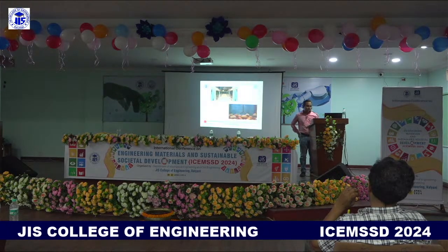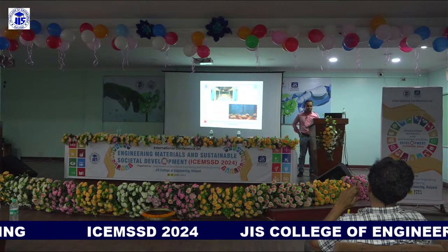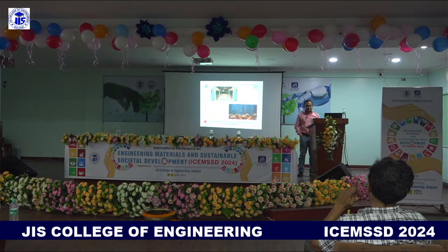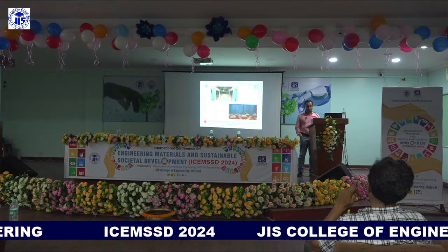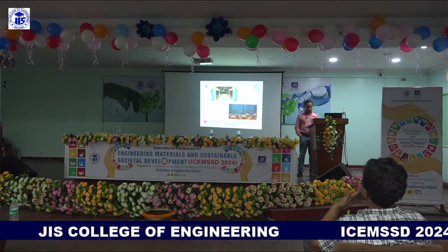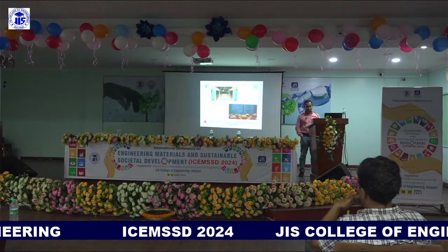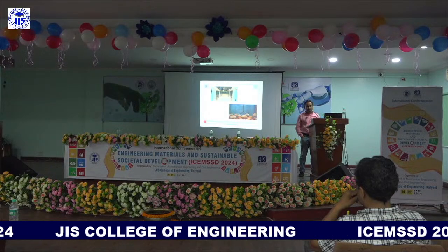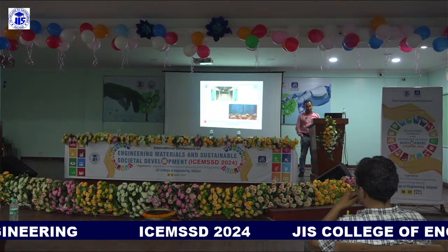For this kind of experiment, initially we use some non-dimensional numbers. In your fluid mechanics book, you will see many kinds of non-dimensional numbers, like the Froude number, Reynolds number, Weber number, Mach number, and so many others. When we want to make an arrangement of the river in the laboratory, we fix the experimental parameters by fixing the Froude number between the laboratory and the field.